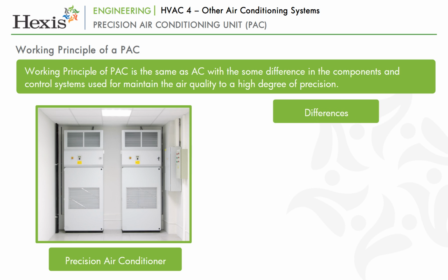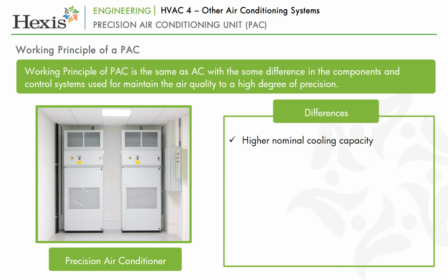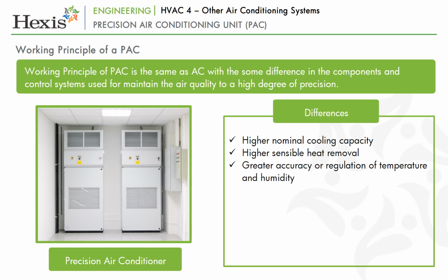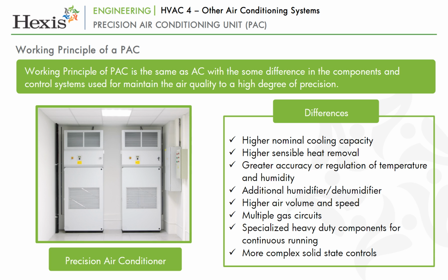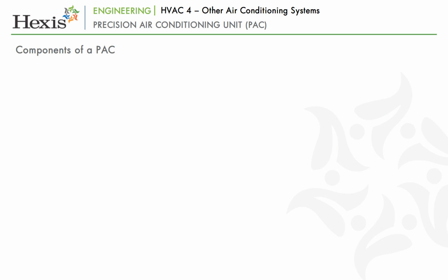The differences being higher nominal cooling capacity, higher sensible heat removal, greater accuracy or regulation of temperature and humidity, additional humidifier or dehumidifier, higher air volume and speed, multiple gas circuits, specialized heavy-duty components for continuous running, more complex solid-state controls.